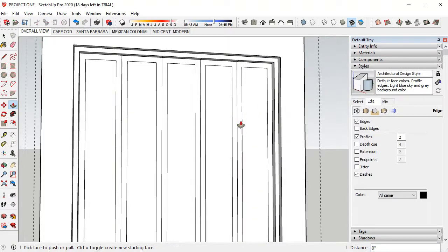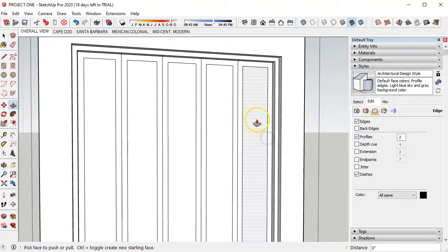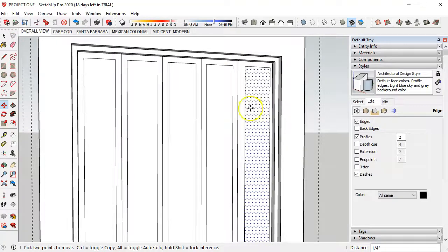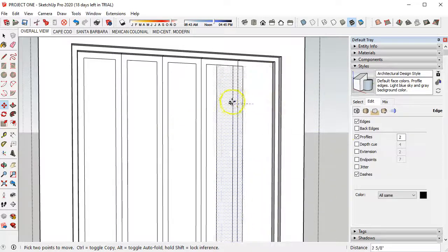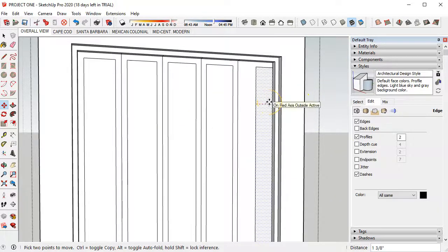Okay, or let me show you what you can do. You can move these panels and give this a bevel. We really are not set up that way, but it's going to look a little odd here in the middle. But let me just show you on making bevels. So if you go to the Move command and select this panel here, the surface, you might not be able to do it with your mouse just moving around, because we need to move forward, not in the red axis direction, but in the green. So tap your left arrow button and then you can move it.